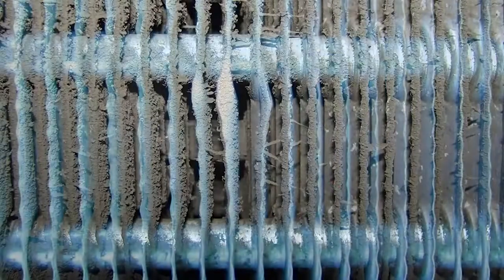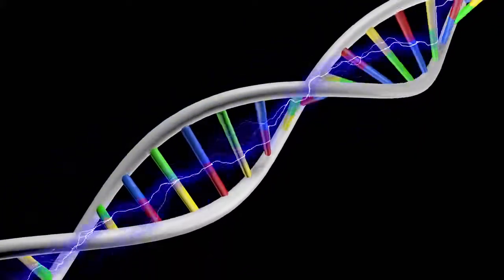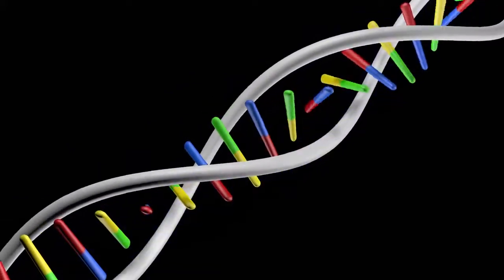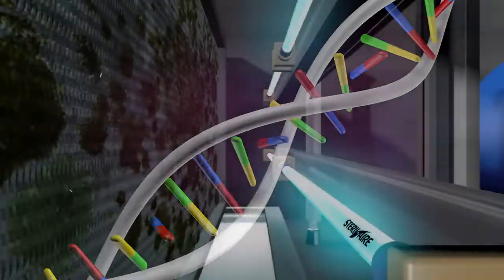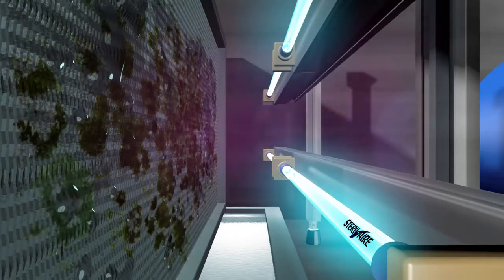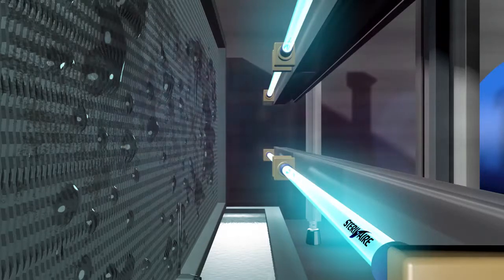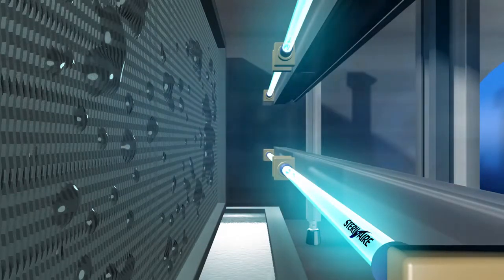Sterile Air's emitters continuously clean the coil fins by destroying the DNA inside the microbes. Once the DNA is destroyed, the microbe can neither grow nor duplicate, so it dies. The dead mold falls away with the dirt and is washed by the condensate into the drain pan.